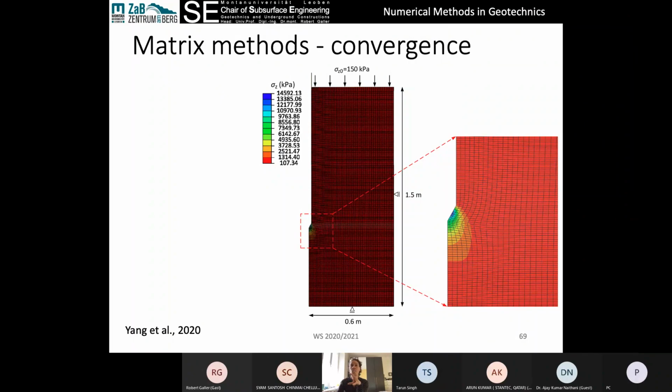A finite element code can't actually demonstrate failure because it's a small strain, so it can't actually cause squeezing or full-on failure like a discontinuum code can. What it will say is, I can't converge because the accelerations are too much, things are continuing to accelerate according to perhaps gravity or whatever it is. And that's an indication that your excavation might fail and you have to come up with some other design solution to prevent that failure of the excavation.